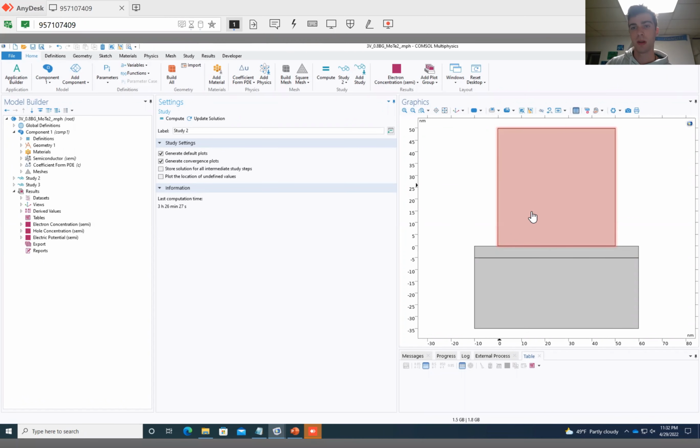Our oxide is actually a polymer electrolyte that contains mobile ions that can move in response to an applied voltage here at the top. When you apply a voltage, it causes an EDL to build up at the top and bottom of this electrolyte, which induces carriers into your semiconductor layer here. This is a silicon dioxide layer, inert, that doesn't have any carriers within it.